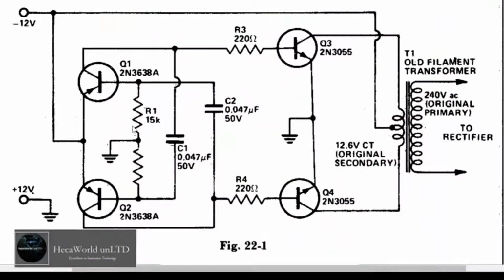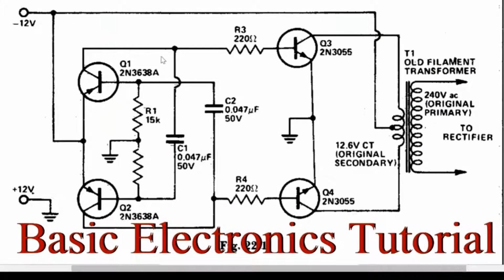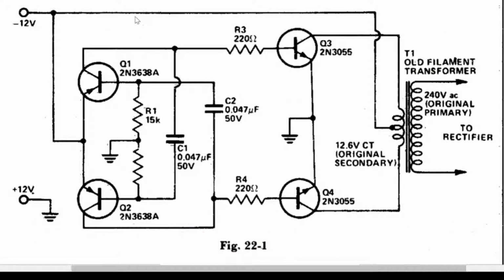The emitter actually connects to the positive. You can see plus 12 volts. So it fails this test right away. The emitter is not the most negative. The emitter is the most positive. For the PNP transistor, the emitter should be the most positive. Did it pass or fail the test? We're looking at most positive for the PNP. So this PNP transistor, looking for most positive, no, it is the most negative. Or the more negative, because you have just two terminals here, but you get the point.